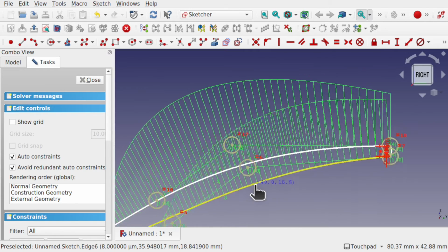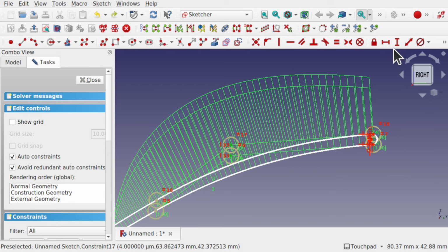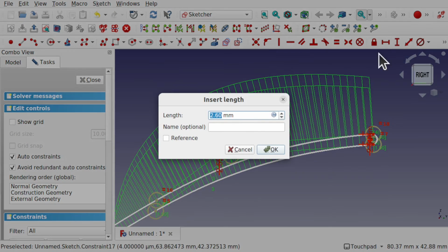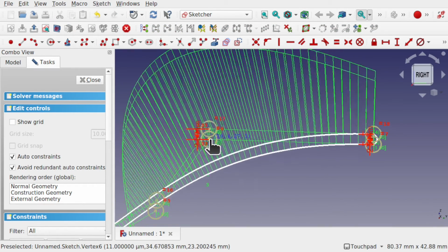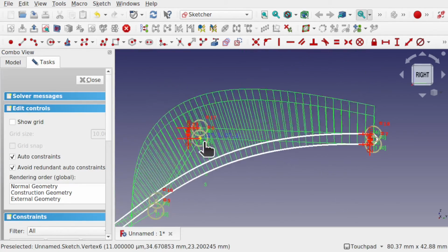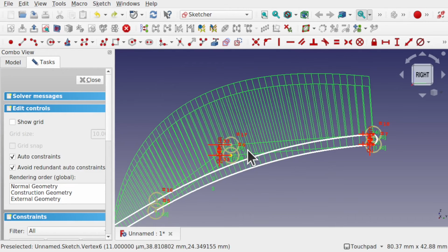So these still can be pulled away from each other. Control Z that. Now we can take these two, place a height 2.5. So you can see as I move that, that moves and keeps that distance away. And we repeat with these 2 points.